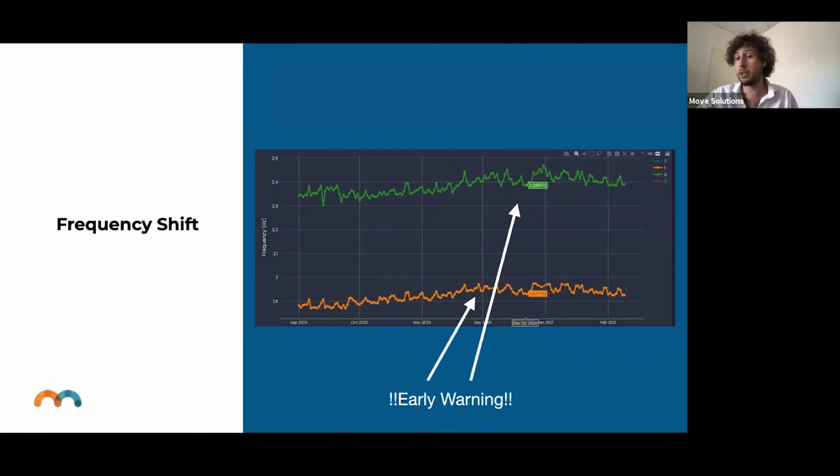That was a really good thing, because, I'll be real quick with the story, they saw that basically the pre-stressed cables were starting to get loose. We understood it before, using the frequency analysis, because we were seeing that these frequencies were changing too much.